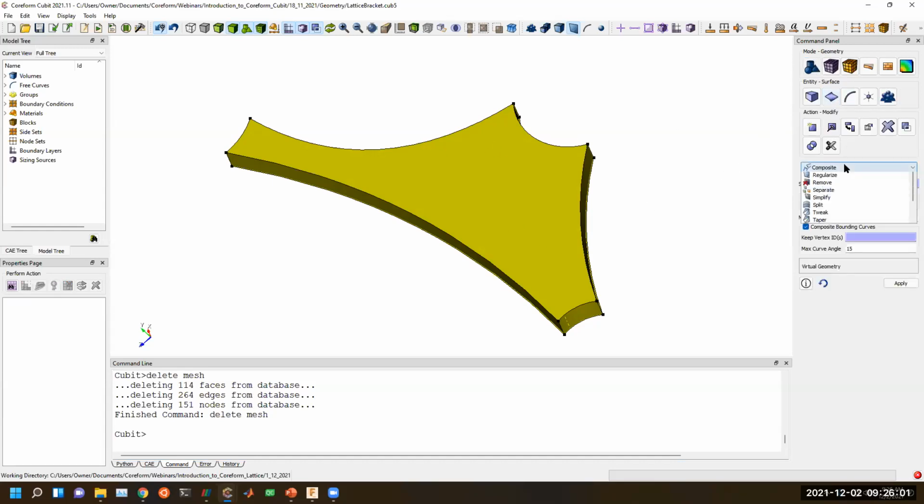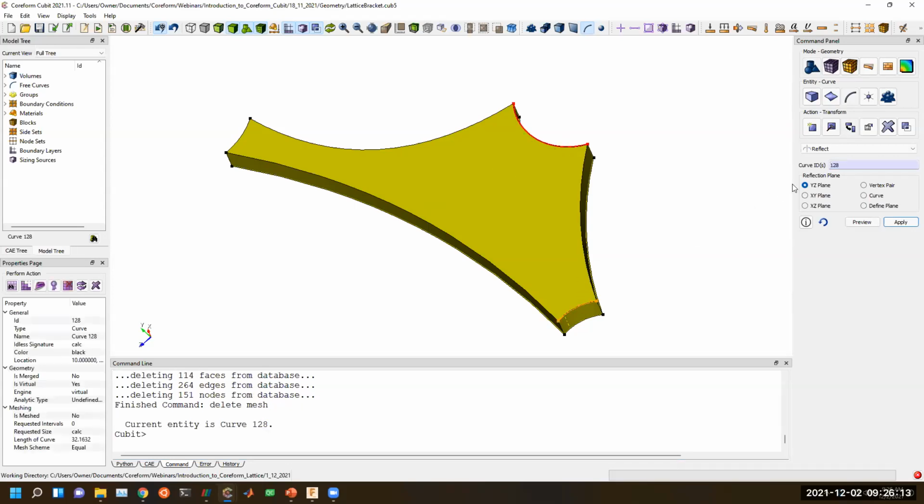So again, in preparing the CAD model, I'm going to split curves. I'm going to get a dividing curve that divides maybe these faces in halves. So I can take a curve, modify, partition, and cut it in half. Or actually, I guess this is what I do: I add a vertex on this curve.